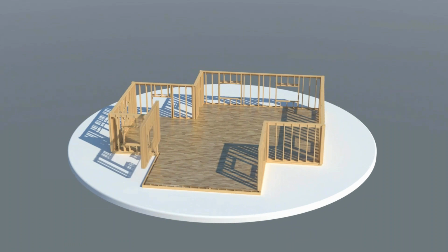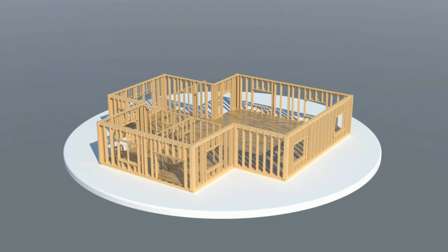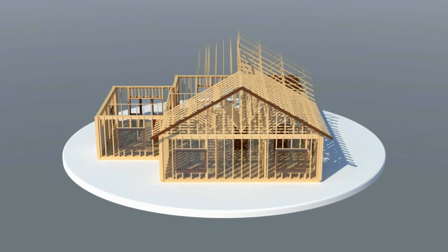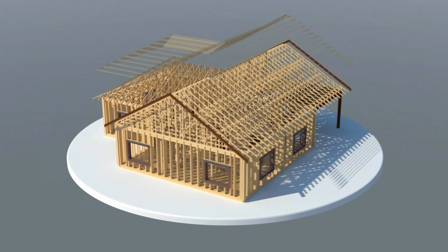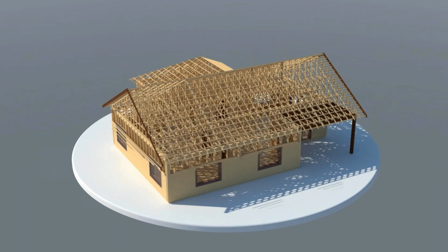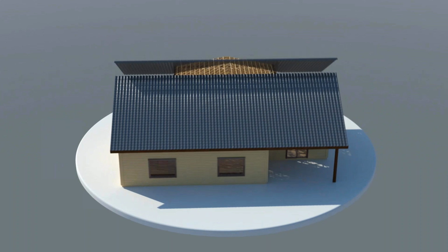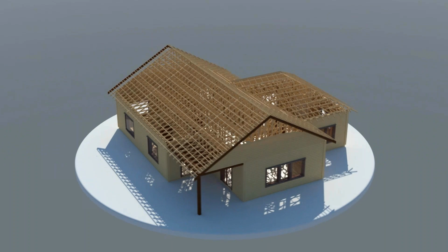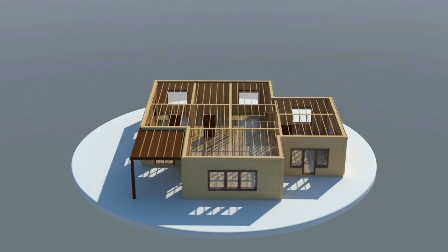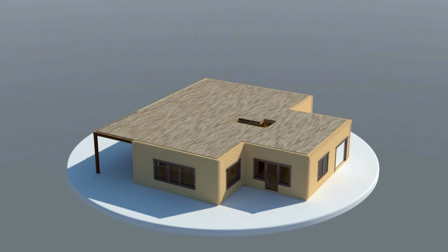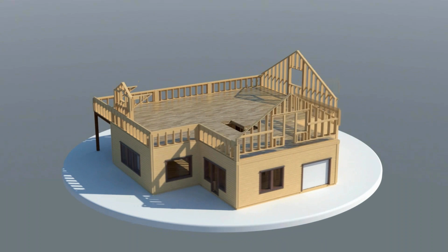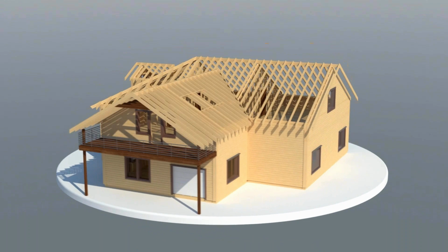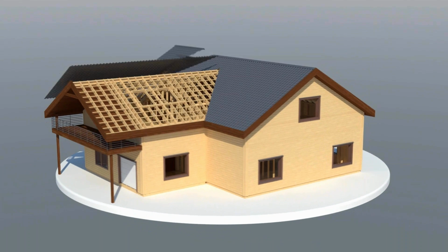where you can automatically predefine and make prefabricated wall panels with different layers. Actually, it doesn't matter, they could be different types of layers in the wall. And here we have a truss system together with battens, with sidings, which is automatically generated. And of course we can make one more scenario. Let's make a second floor, and then we can make one more roof system using rafters, not trusses. So again, just one more scenario with a different roof type.